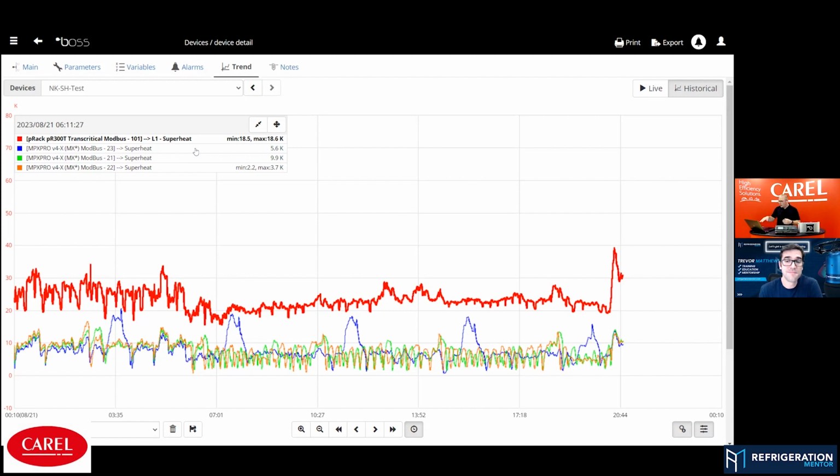Maybe you can ask, why did you insert the superheat from your rack, so the superheat of your suction line? Pretty simple, because if I'm optimizing my superheat and lowering it more and more, I would like to avoid bringing the superheat in front of my compressor too low, or giving my compressor some liquid. That's the reason why I brought all this information into one log graph and looked at everything at one time.